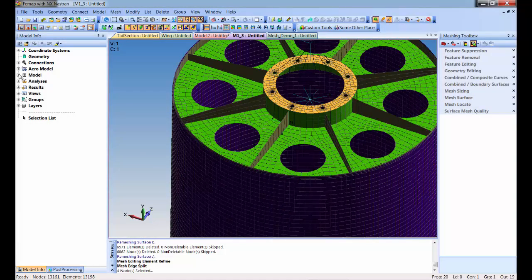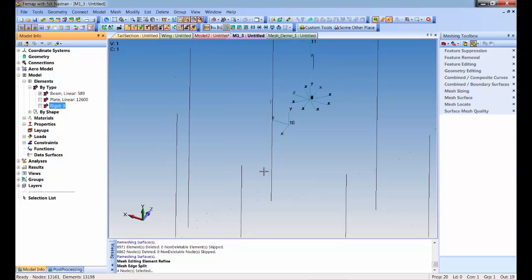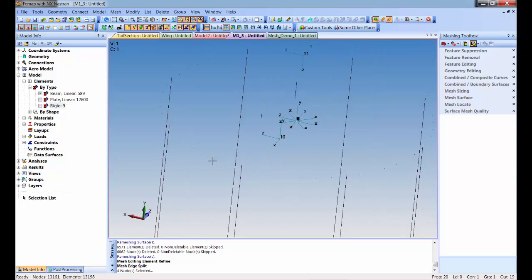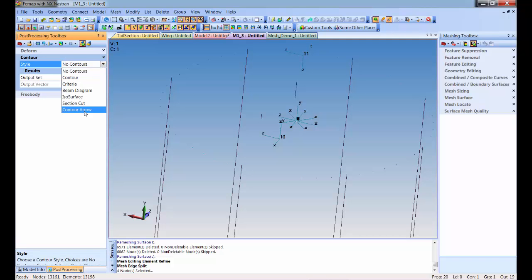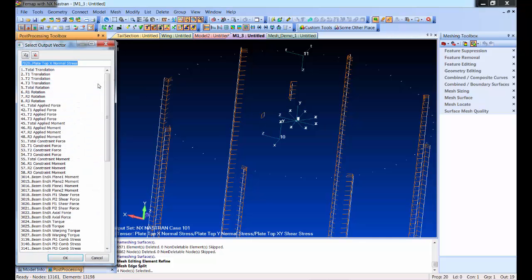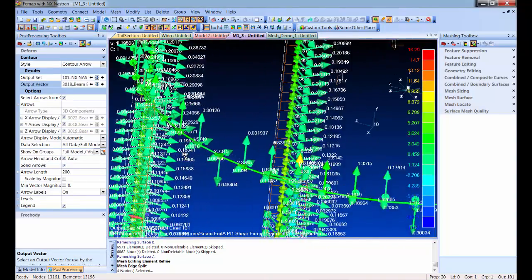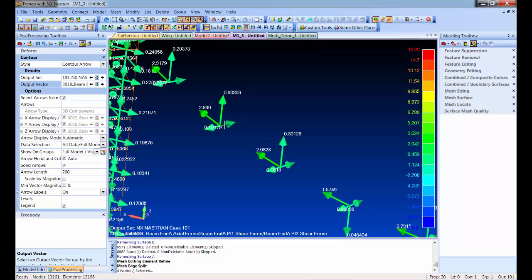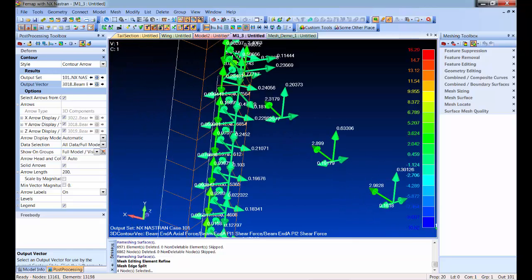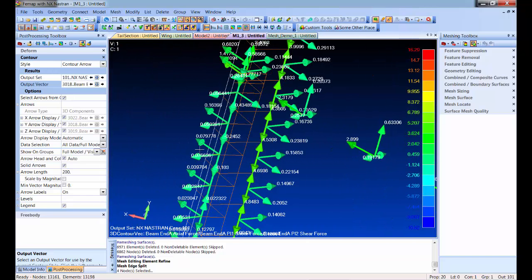What I'm going to do is some beam ones real quick. I'm going to shut off everything but my beam elements in this model. You can barely see them, but there are little stiffeners running vertically, and little fasteners running this way. So if I go into the arrow plot and pick shear force on a beam, it automatically goes and draws all my beams. So you'll see tension on that little fastener. Here are its shear components. And the bigger one, same thing. You'll see tension and shear.